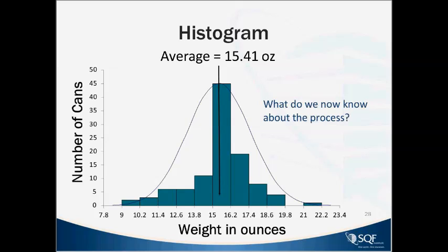It doesn't work. There's a lot of other problems that you've got to do, so you've got to go back in the operation and fix them and get some sort of normalcy to your data. And that's what the histogram allows you to do. By collecting the data and looking at it, you can say, hey, I have a normal distribution, I have a stable process. It gives me some sense of what I can do to change the process if I want to change the location of that histogram. So it represents your population and represents the type of measurements that you're doing in your process.